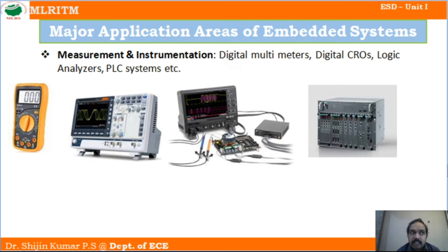That signal is converted into digital form using an analog to digital converter. Then it is given to a display, and we can see 1 kg or 2 kg or 1.5 kg displayed. It is more convenient than a normal weighing machine. Previously we had weighing machines with a needle, which may not be precise. With this one we can get up to 3 decimal places, like 1.125, that is 1 kilogram plus 125 grams.